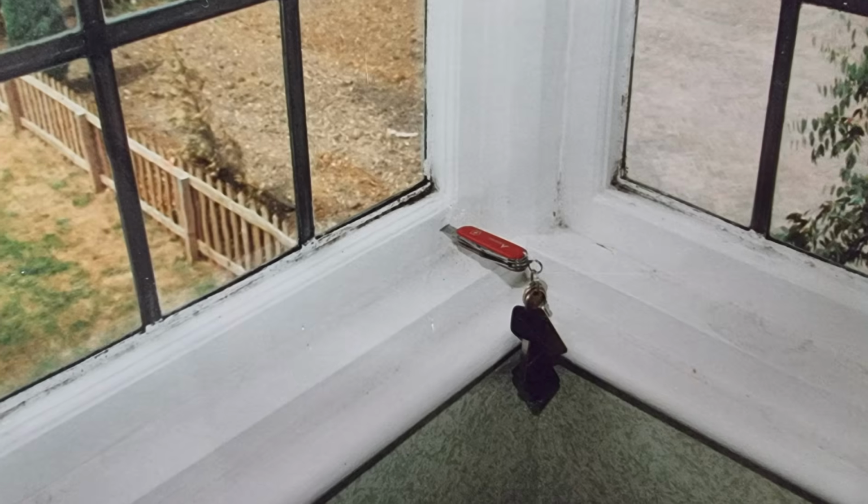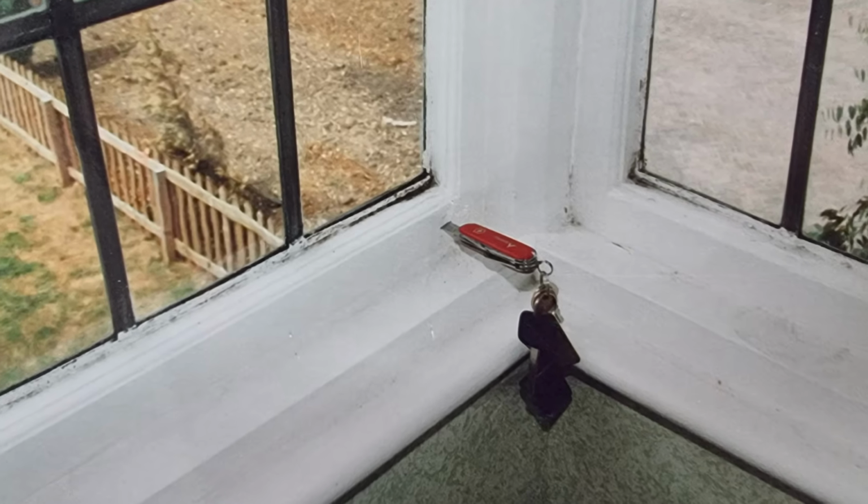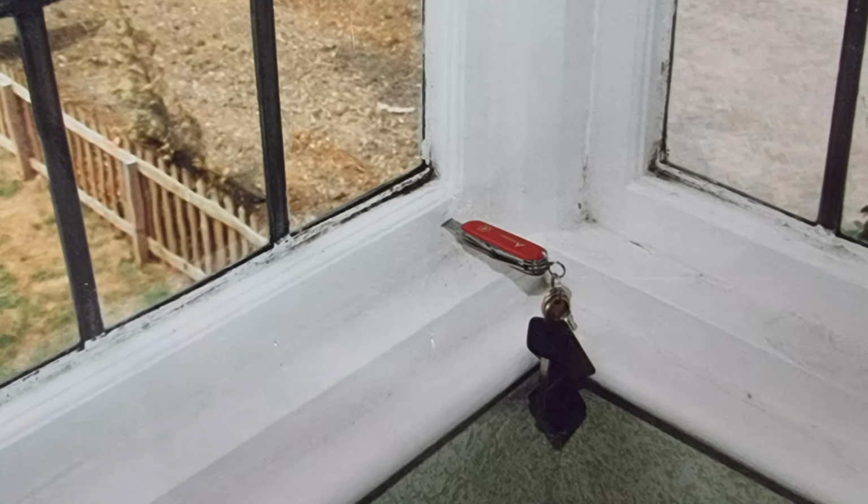Well, the first stage of investigation, once you've established you think you've got a problem, then the next thing is to very carefully probe it. Now, I generally carry a Swiss Army knife around with me, and so I'd pull out one of the blades and gently push it in and see if the surface was going to give, if it was beginning to deteriorate.